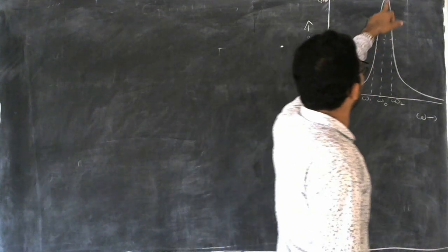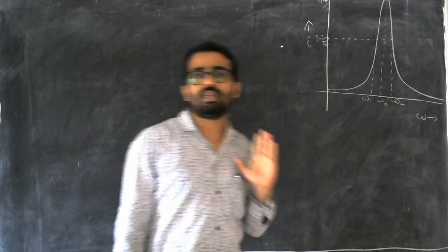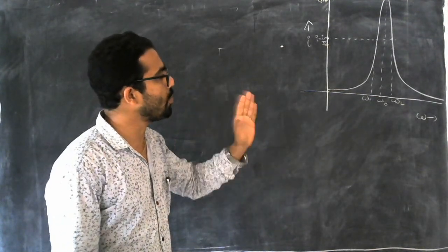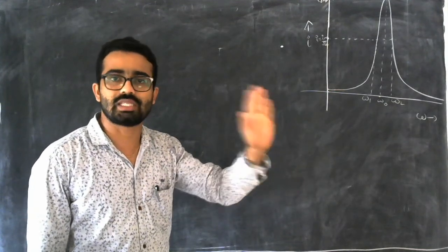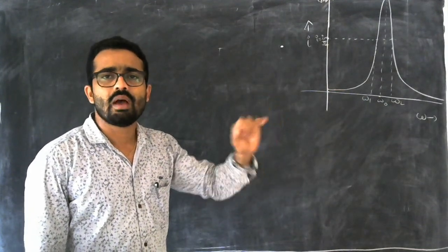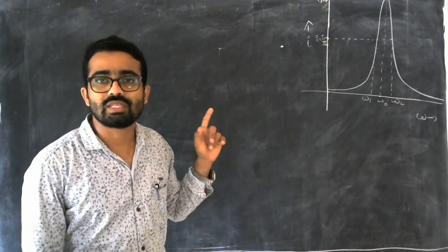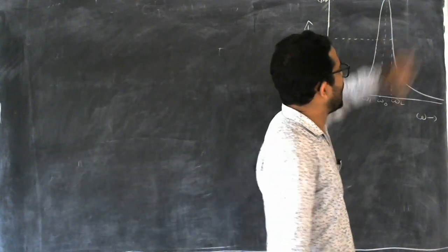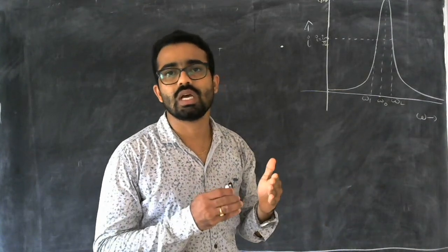Because when the current in the circuit reaches a maximum, at that condition Xc is equal to XL, so the power dissipated in the circuit will also be maximum. There is a maximum power dissipation in the circuit at the resonance condition, which is actually through the resistor.